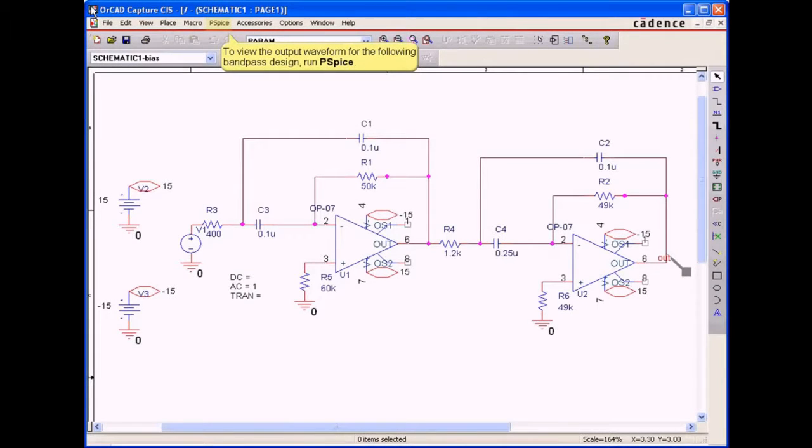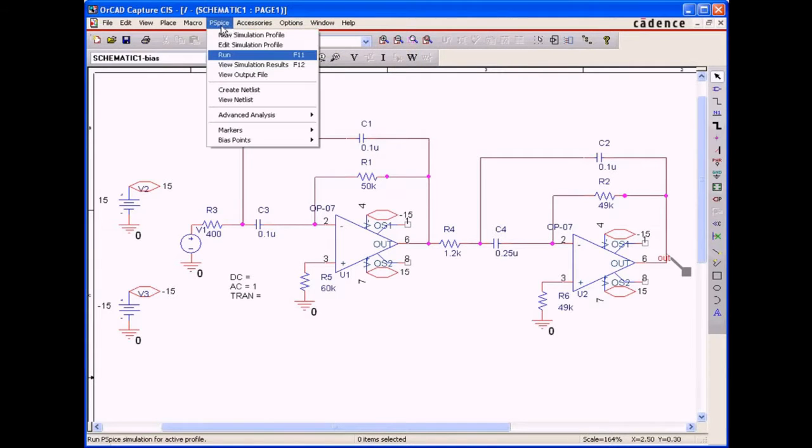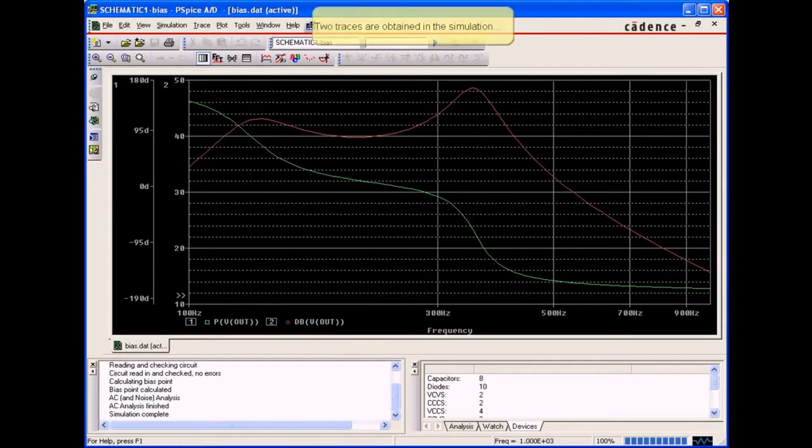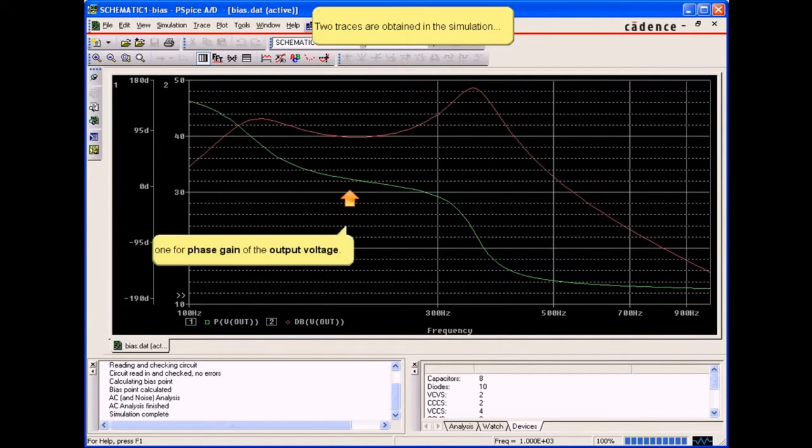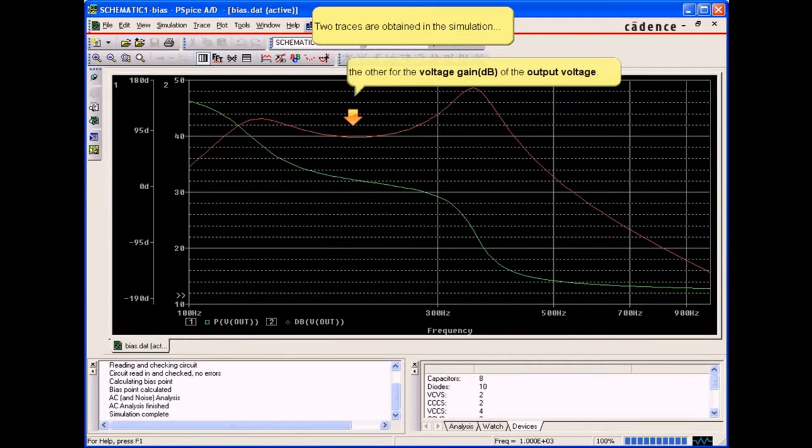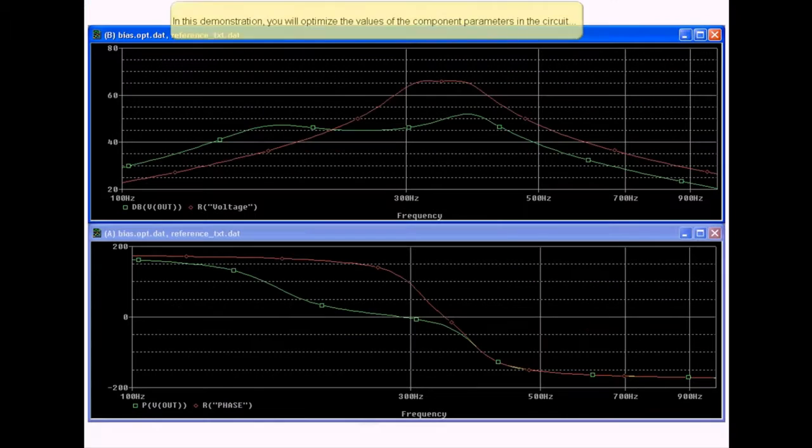The example design seen here is a bandpass filter, and the design specification will be represented using XY points. The objective here is to optimize the phase margin and the gain margin. Using two separate specifications, not only will we try to optimize the design against the two curves, we want to curve fit the design output to both of these reference curves simultaneously.